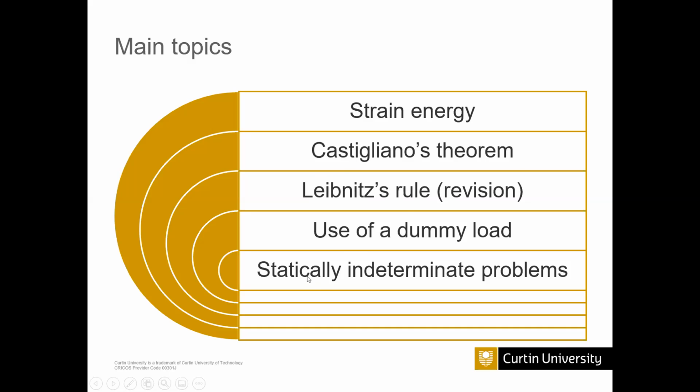In the Castigliano theorem, there is a way to find the deflection at a particular point. When we find the deflection at different points, you need some kind of load at that point. Normally we use a dummy load if there is no existing load at that point. That is the use of the dummy load. You will see the different approaches using this theory during this topic.